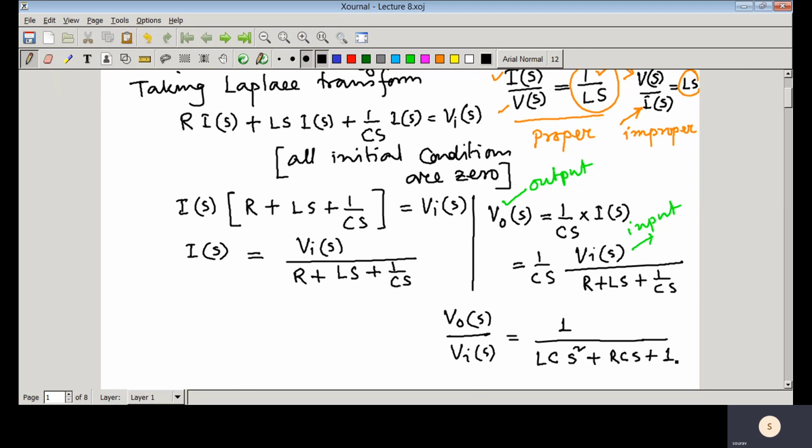So this is the transfer function from input to output, and we get it by applying the Laplace transform and considering all initial conditions equal to 0. I hope now it is clear to all of you how to find the transfer function for any physical system, linear time invariant dynamical systems. Of course, the transfer function based modeling technique is only applicable to linear time invariant systems, as we have already discussed in detail.